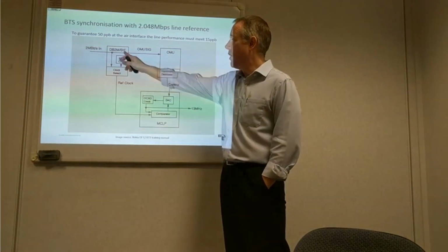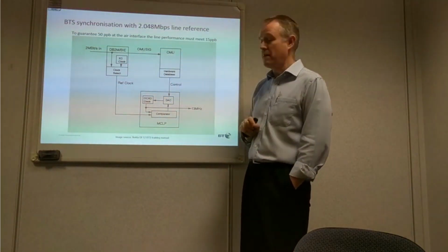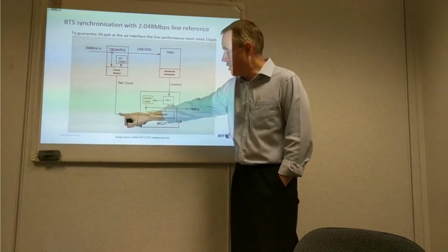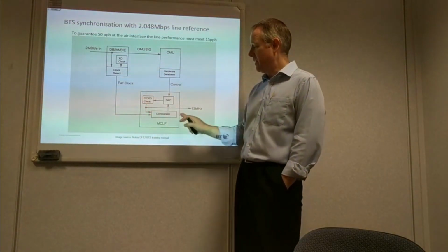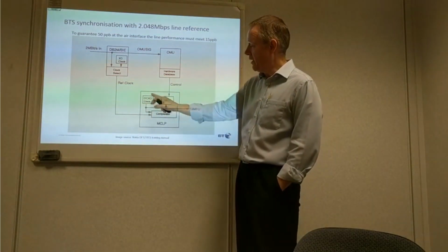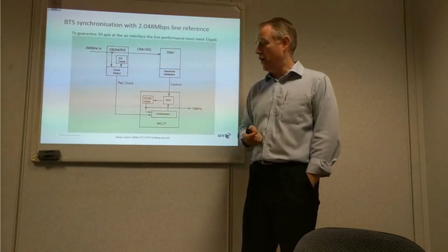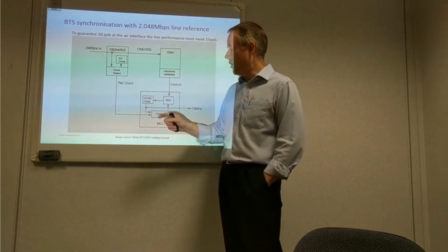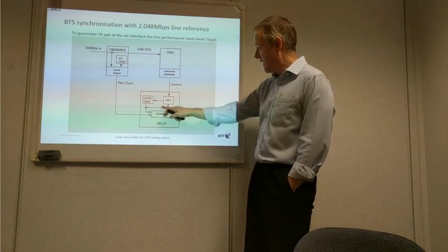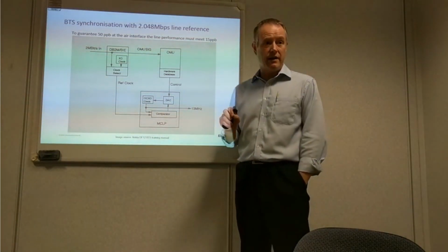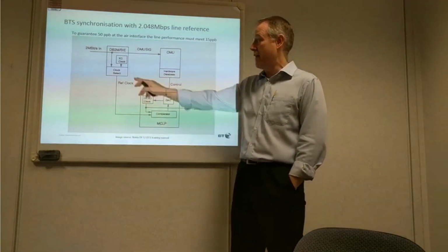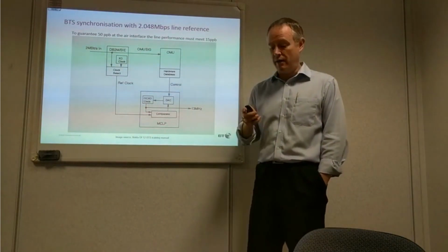We've then got an OMU signalling link going through to the operations and maintenance unit where we've got the hardware database, and we've got a reference clock that feeds into a comparator and effectively a phase lock loop where the digital word value feeds that OCXO. Okay, so we've now got an oven controlled quartz oscillator in there, and the outcome is 13 megahertz, and we can keep that clock stable through this loop and the reference we've got on the E1 line itself.